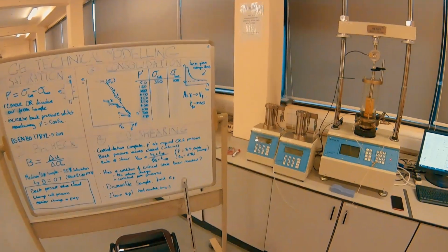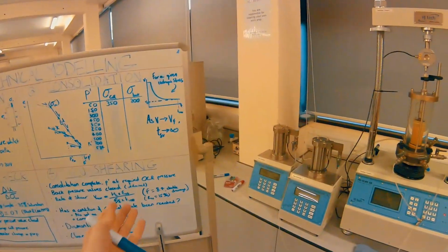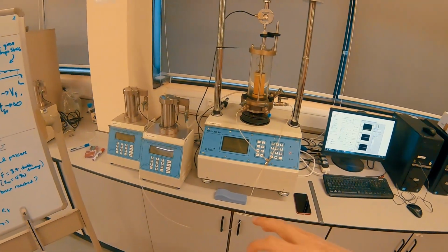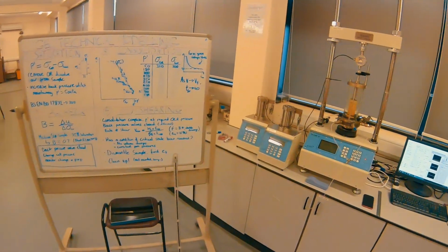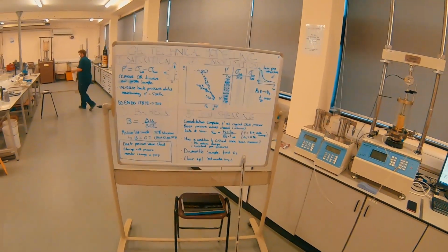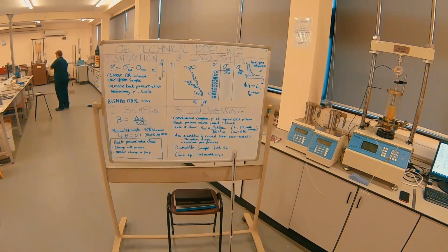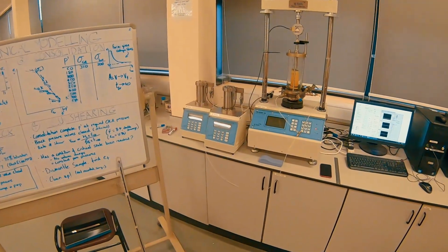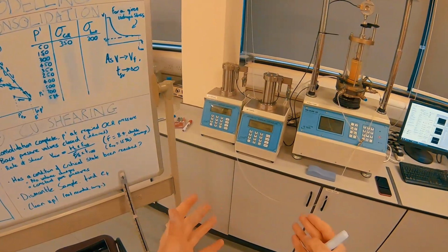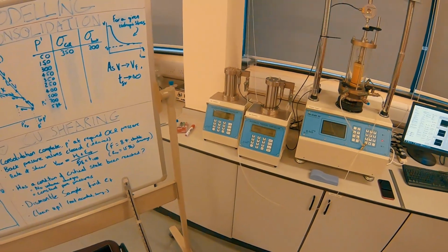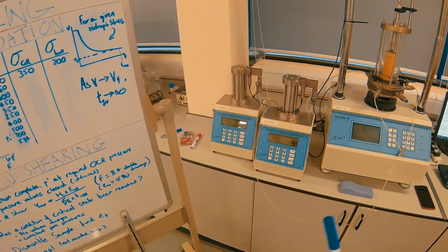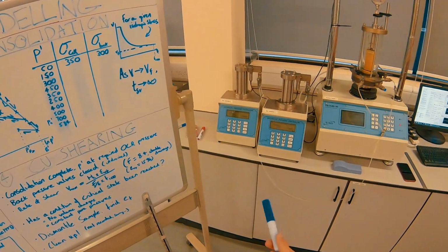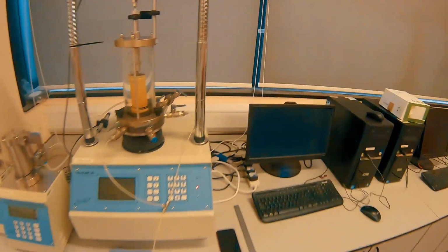There are two things you can do. You can either keep the back pressure the same, or you can increase your back pressure, further compressing the air within your sample and forcing it into the water solution. For our purposes, we are limited by the ability of the stress controllers, the pressure controllers. We have a maximum pressure on both controllers of 1,000 kilopascals.